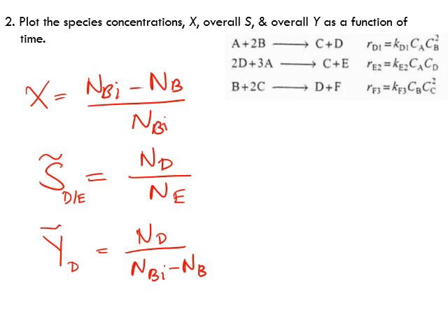Okay, we need to frame all of these, and we need to make sure how to define Nbi. For instance, we said already Nbi equals Cbi, the concentration of pure B, 2 mol per liter, multiplied by Vi, which was 40 liters. One more thing we need to be aware of: this value equals infinity at time 0, because at time 0 Nd is 0 and Ne is 0, so 0 over 0 is infinity. The software will be jammed and cannot proceed with a numerical solution.